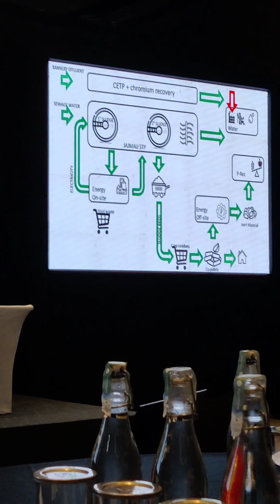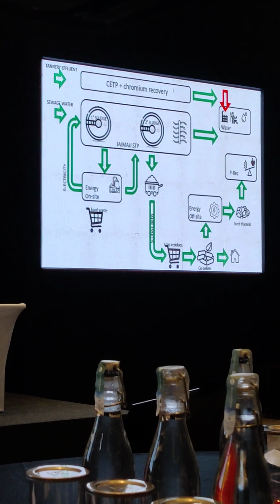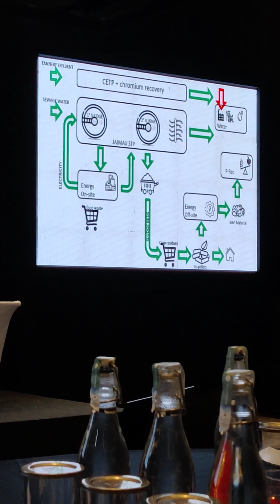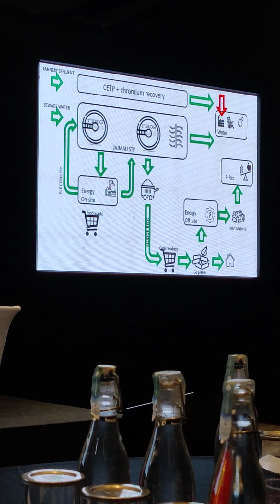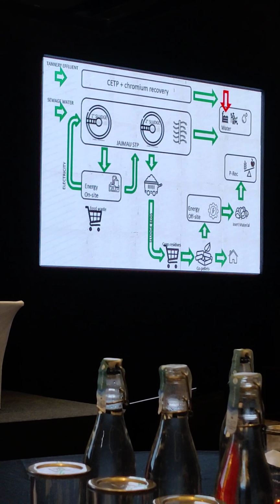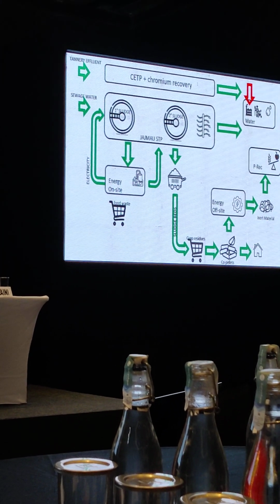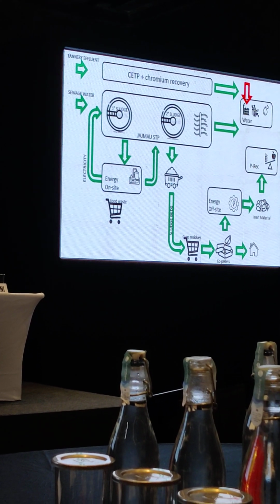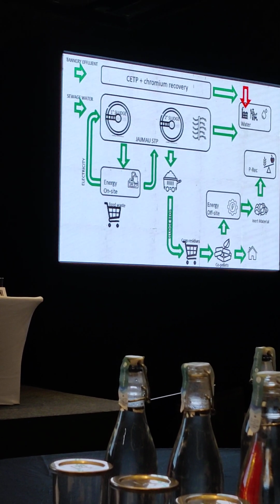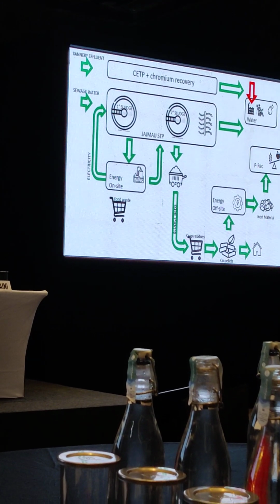So at the end, what we're proposing is the following. The tannery effluent: there shouldn't be any legal discharge, theoretically. The CETP will be equipped with chromium recovery. This is a fact. They're already working on it. It's actually under commissioning. The sewage plant would be treated, of course, in the Jajmau STP, and what matters in this presentation is to have primary sludge treated and enriched by food waste, and the secondary sludge would go to the sludge drain beds.